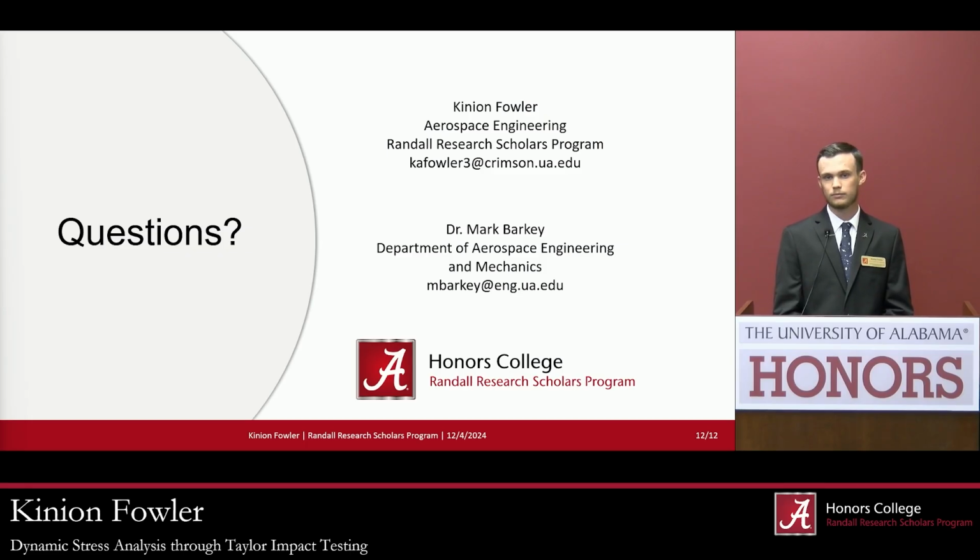So what kind of velocity do you target, and why? So the target velocity is going to depend on the sample we're testing. As I showed in the diagram previously, we need to have a section where it goes from plastic deformation to elastic deformation. If it deforms completely elastically, the test is not useful, and if it deforms completely plastically, the test is not useful. So we need to have a velocity that's in between. Typically, this is in the range of 100 to 400 feet per second, but it depends on the material.